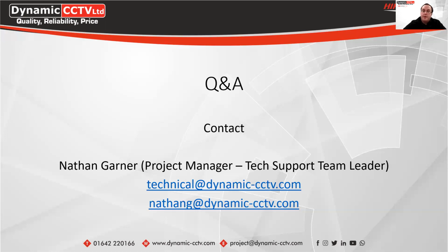Paul has asked, are you able to explain a bit more on how POC works and what can be done for fault finding, etc. please? So in the actual menu on the recorder itself, if you go into camera, there is a POC information page. Generally what we'll find is the camera's not powering up, or you're not getting a video signal from the camera itself. If you go into the POC information page on the NVR, or DVR should I say, it will actually tell you if the camera is drawing POC power from the recorder.